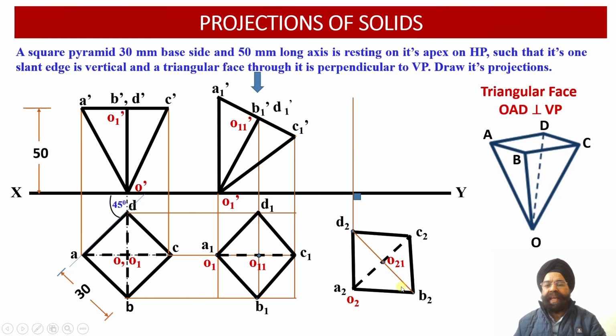How can that be done? Once the observer looks at the solid from this direction, 6 points are available. Through these 6 points we draw vertical projector lines into the elevation projection view, and wherever these vertical projection lines intersect the horizontal projector lines drawn through the elevation projection points from the previous elevation view,